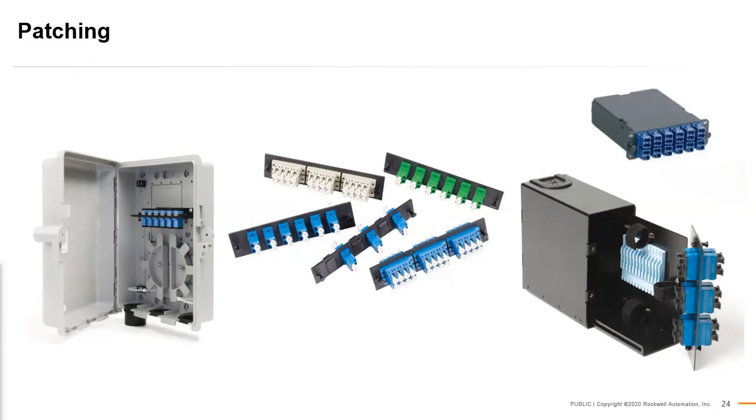And stay on this one just for a second, Joe. I want to point out, because I see a lot of fiber installations where people are just using basically a long patch cord going from A to B. And we'll get pushback sometimes saying, well, if I put a fiber enclosure or patch panel there, all I'm doing is degrading the system. Well, the cabling standards allow for this. Every time we mate 2 fiber optic cables together, let's say through one of these bulkhead connectors we see in one of these panels, we're going to estimate, and I'll be conservative, we're going to lose like 1.5 dB of power in our budget. And that's someone who does very sloppy work. You can do much better than that.